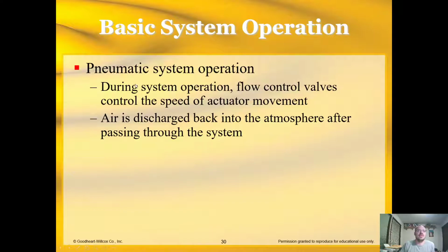So I did miss one. During system operation, you have fluid control valves that control the speed of your actuator movement. So you see a lot of similarities there between your pneumatic and hydraulic systems. But again, there's a little bit of a difference with where it's really drawing the fluid from. In this case, pneumatics draws fluid from air, where hydraulics draws its fluid from a reservoir.